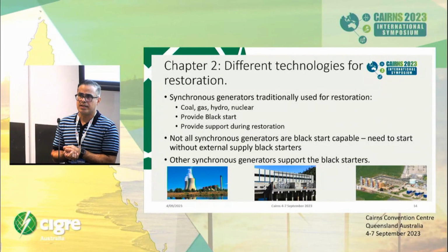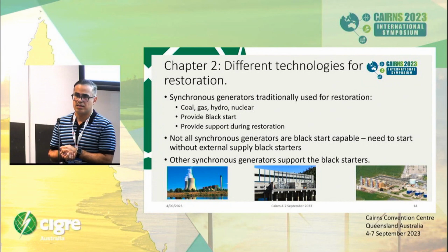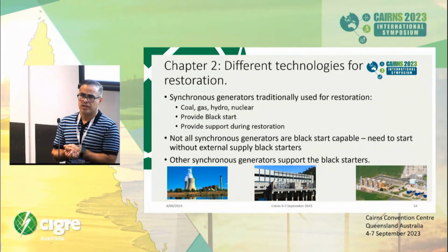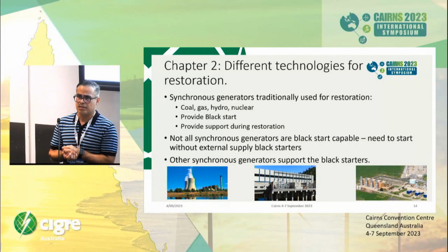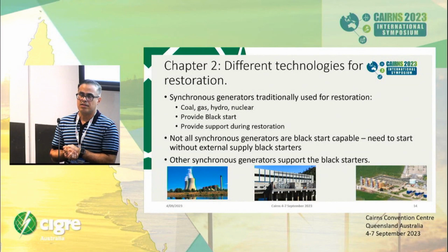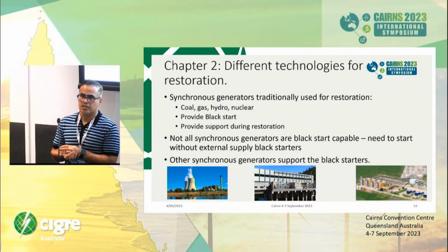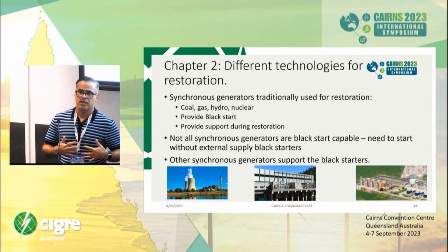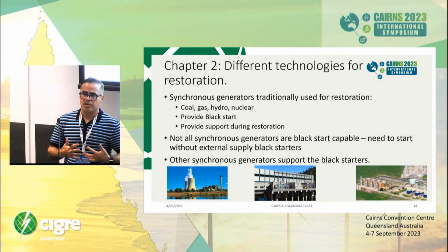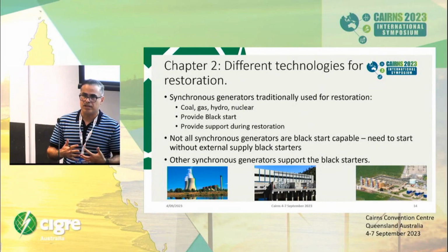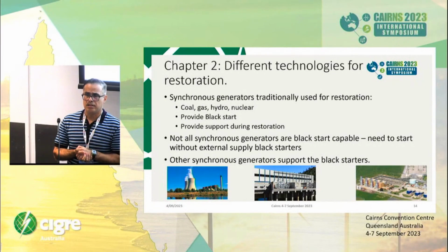And then the next level, anything that indirectly or partially uses current. You have, for example, negative sequence protections that they used in some directional relays. And then you go to distance protection that still uses current, and that impedance might get lost. And the question is, maybe we should consider more the likes of differential protection and other types of protection, because it's much cheaper to upgrade protection than upgrading the sources of generation to make sure this relay operates. But the problem that you're stating is a very genuine and important one.